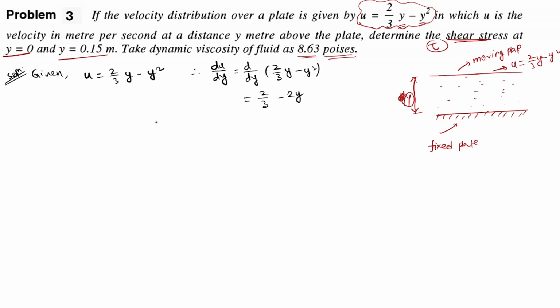After that, you can easily find du dy at y equal to 0. What is this at y equal to 0? Because you are asked to find the tangential stress. This is the asked parameter. So how do you find that? Tangential stress is equal to mu into du dy. So you will need du dy.